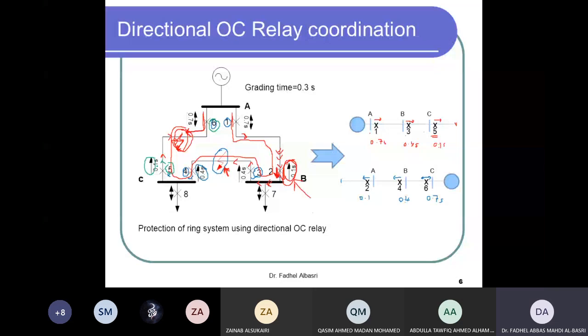So there'll be no flow of current coming from 1 to the fault points because of opening breaker 5. And now breaker number 6 is the only one that will keep feeding the faults at this point. So now once 0.7 reach, then 6 will also open.